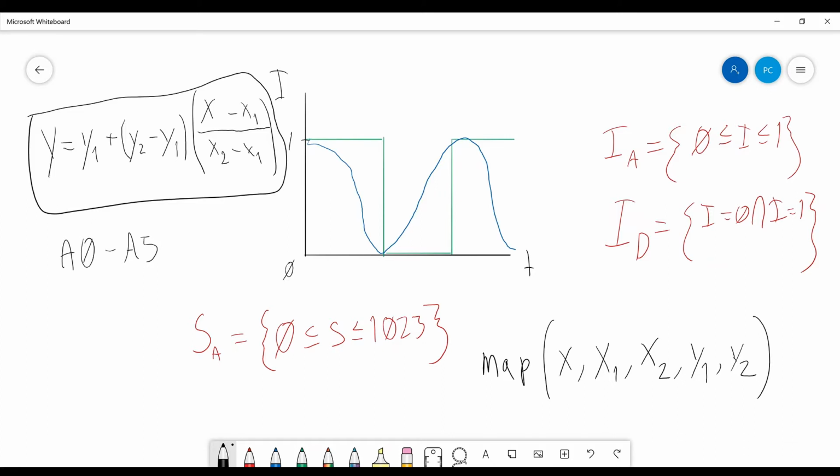So, what about distributing them? It has that too, because these analog pins, they only sense, but they don't distribute analog signals. And so what you have instead is that some of the digital pins will have like this squiggly line. That's where we have something called PWM, pulse width modulation.